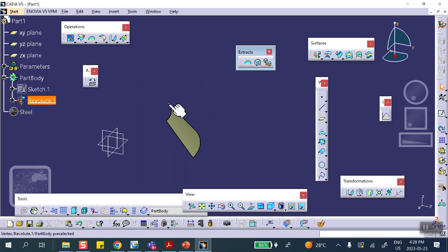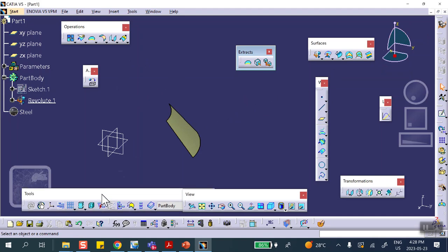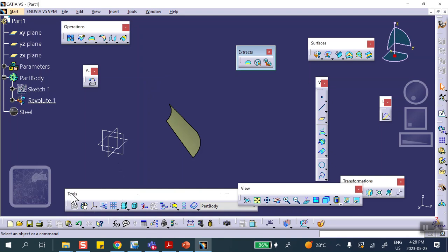Okay, now I made it 40 degrees on purpose because I want to use the coordinate system up here later. Well, I can do that now. This edge happens to be in the vertical plane, in the y-z plane, so I have no problem with it. But the back edge, this edge in the back, is in none of these planes. So I'm going to create a local coordinate system, and this is done in tools. Remember, it's done in tools.